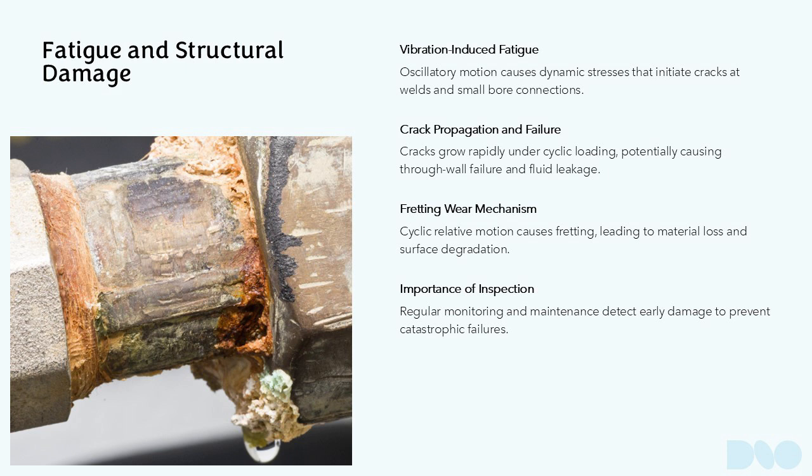The fatigue life of a component depends on factors such as vibration amplitude, frequency, material properties, and the presence of corrosive or erosive conditions. Intermittent vibration can extend fatigue life compared to continuous exposure, but the risk remains substantial.